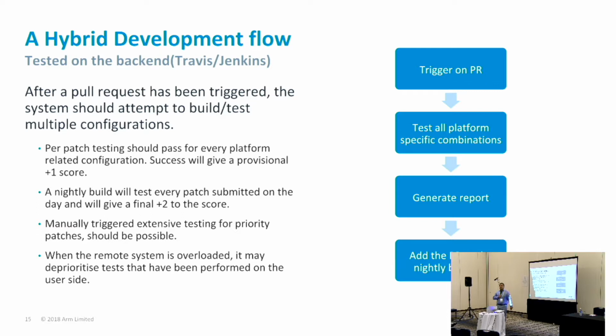And we'll try to test them all during the nightly phase for every single platform configuration. And this is important because you might push a patch for board A, and that works perfectly on board A, but it might totally corrupt the behavior of another board. So it is quite important to be able to use a time window at night to test for every single possible configuration.